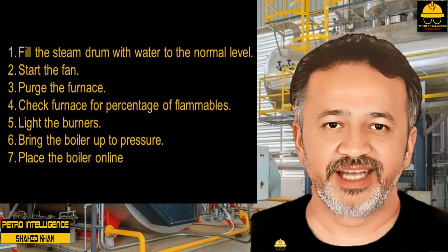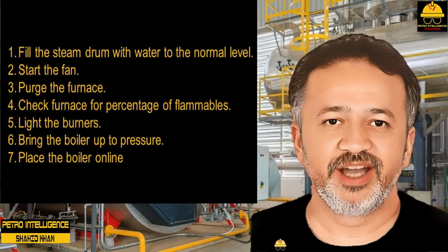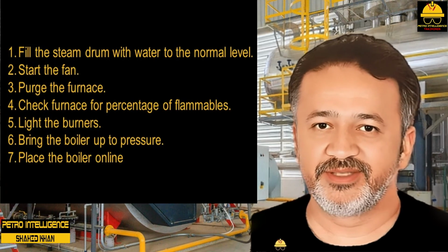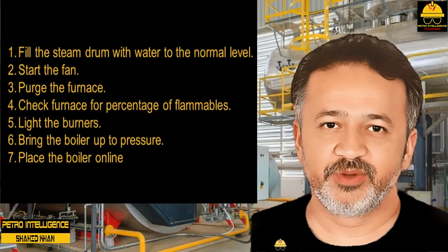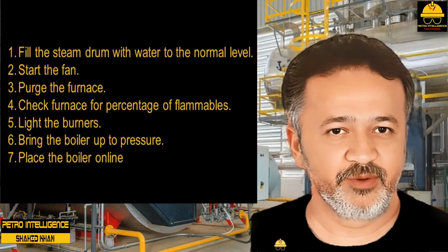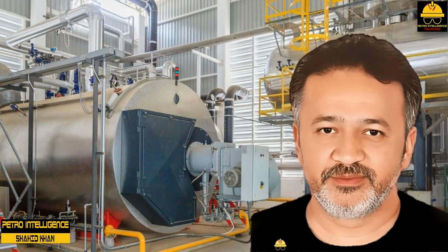The operator maintains good housekeeping and unit logs and checks fuel pressure and temperature and oxygen level. Finally, the operator monitors the pressure of the firebox and drum, the temperatures in the firebox, stack, superheater, and ensures fan operation.